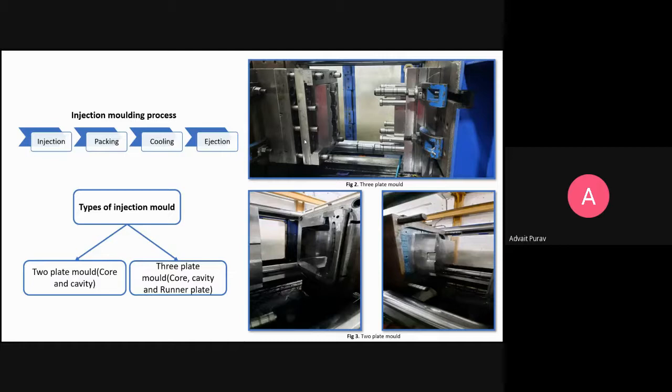So cooling is one of the most important processes in injection molding, because it constitutes around 70% of the injection molding process, and is one of the most major factors in determining the part shrinkage or warpage. What happens is that the deformation that you observe in your part, due to non-uniform cooling or shrinkage, is called warpage.